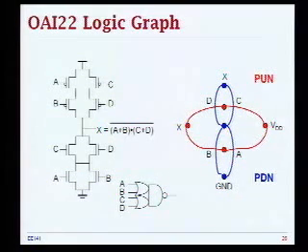One more example over here. It's basically more of the same. You have the equivalent graph. You have A and B in parallel. You have D and C, and same thing. You add nodes to the isolated regions, and you connect to VDD and ground, crossing edges exactly once.